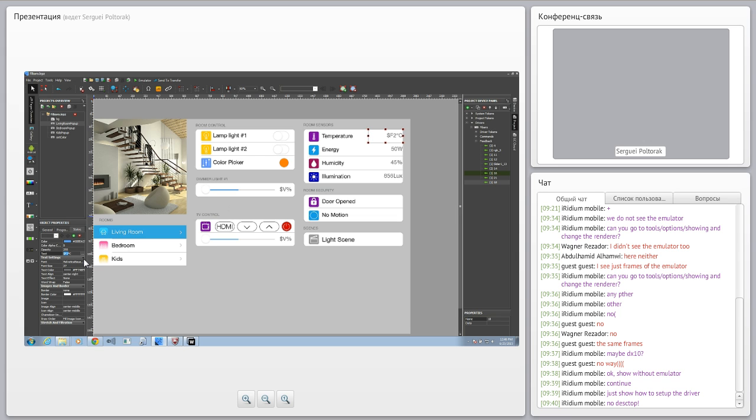In the same way, we need to take the Fibaro device ID of a temperature sensor and drop it on that element. Please note that the scale is written here explicitly, so you can replace it by, for example, degree Celsius or something else like this, or even Fahrenheit, depending on what you have.